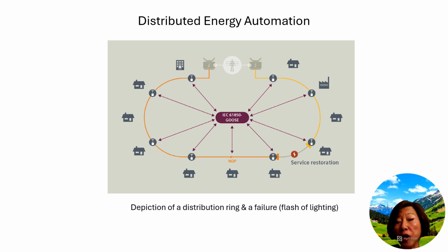Through peer-to-peer communication among these controllers, the system operates autonomously without requiring a regional controller or control center. However, all self-healing actions are immediately reported to the control center to maintain an up-to-date grid status. Typically, the controllers isolate faults and conduct self-healing of the distribution line within 500 milliseconds. You can correct me if these numbers are not entirely accurate, but I think they are.